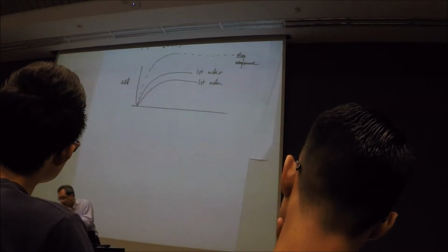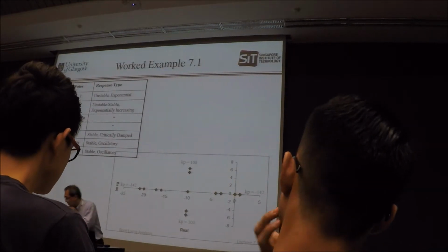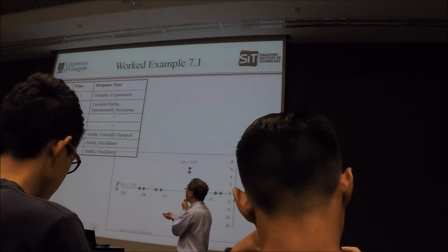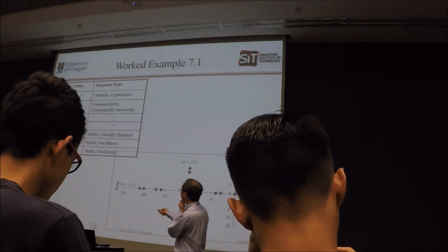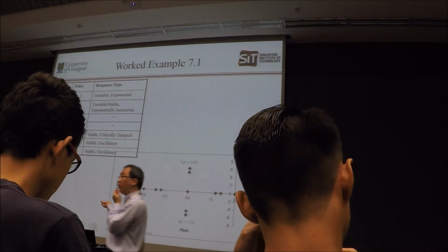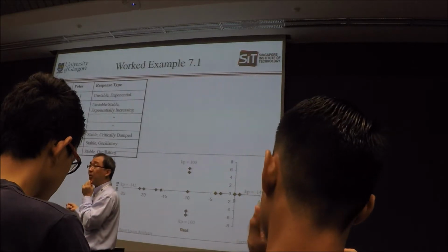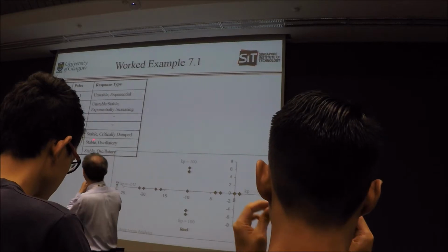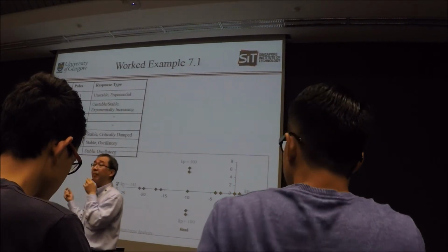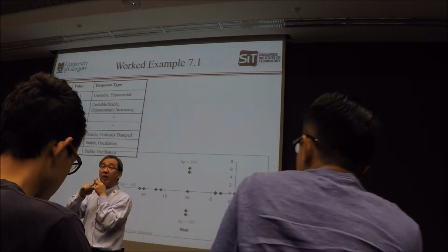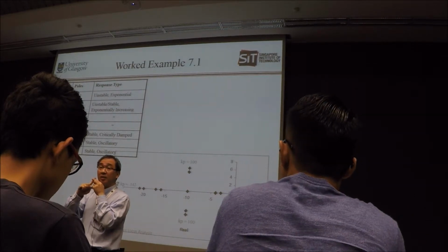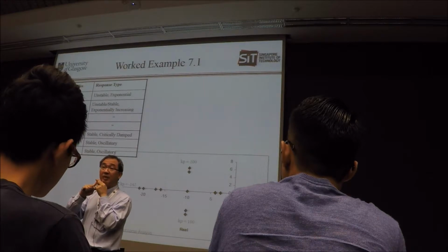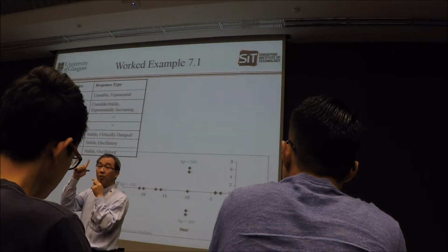So that is basically the step response. Coming back to this, when you increase the Kp value, you reach a point where Kp is equal to 100 and you have two poles at the same location, as we discussed in your second order system. You have a stable, critically damped system, because you have a pair of repeated real roots. That means your damping ratio is equal to 1.